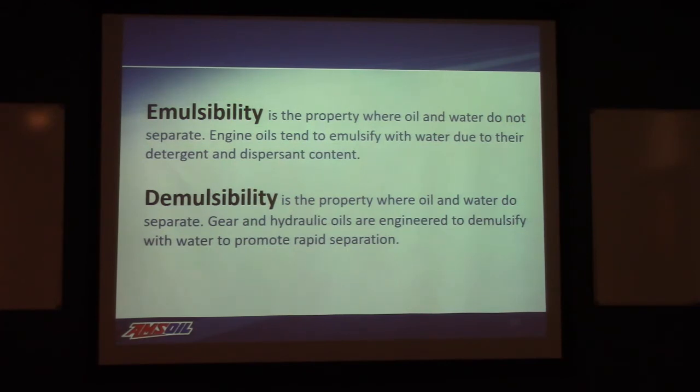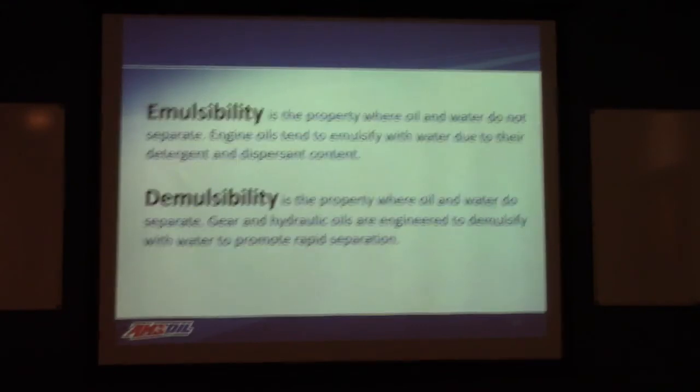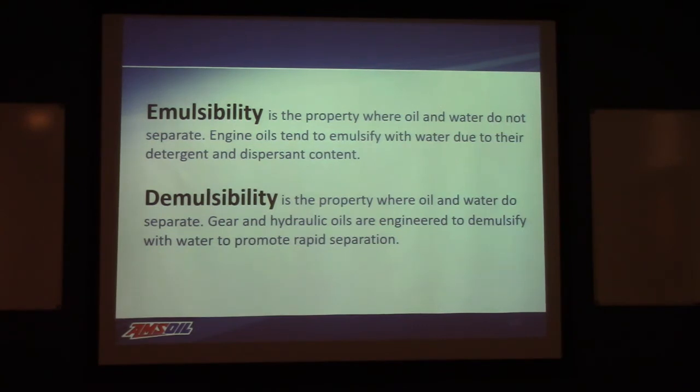What we don't want to happen is we don't want the oil to cause the water to separate. Because then, let's say in the oil sump, that water is going to separate from the oil in the sump itself. And where's the oil going to go? Going to go to the top of the sump. The water is going to be on the bottom. Where's the pickup for the oil pump in an automotive engine? It's at the bottom of the oil sump. You get enough water in there and the oil will not hold on to that water. It will separate. You let it sit for a while, you go to start that engine and it's pulling straight water, pumping it up to the rest of the engine components.